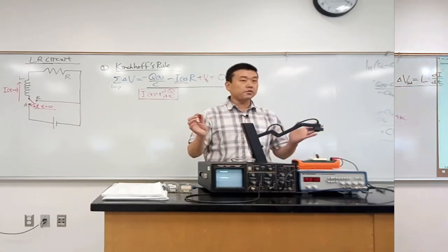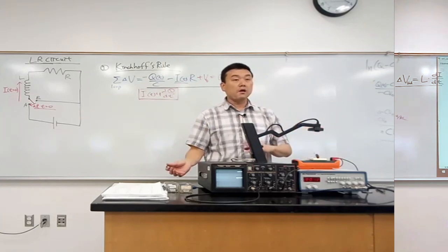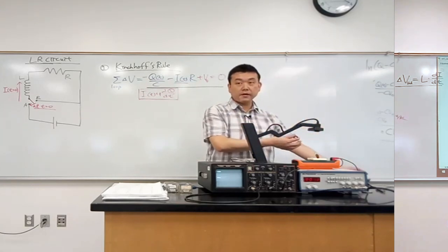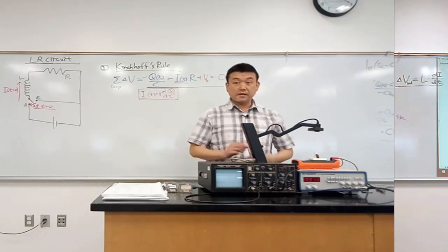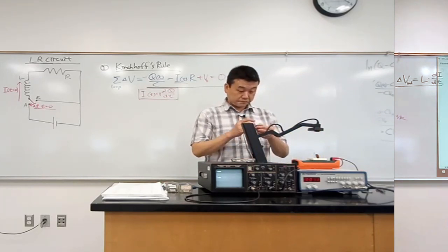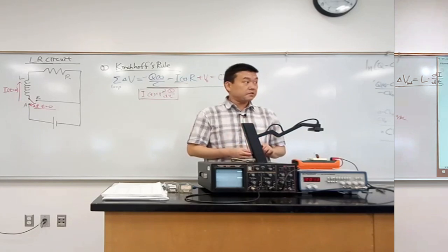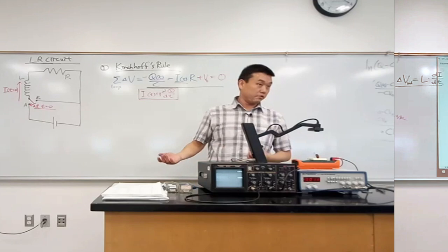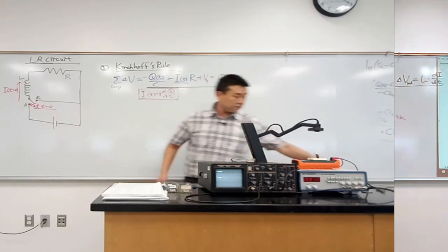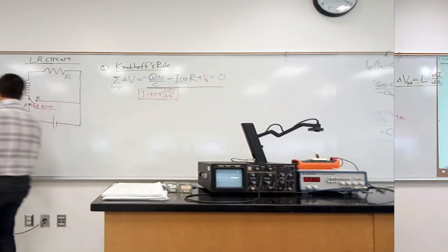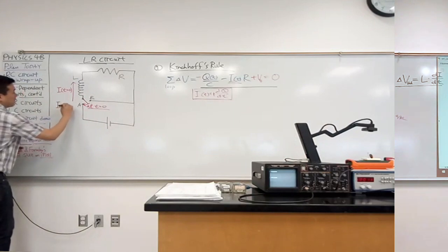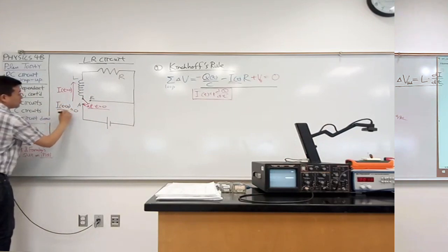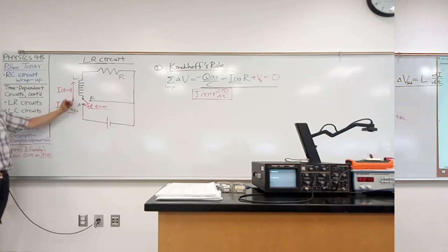Let's imagine all the different values that I could take, one particular value in one category and other values in a different category. Any value you think would be special? Yeah, 0 is a special value for many reasons. Here I can at least give you one other reason than the usual one. The reason 0 is special is the current at time less than 0 was actually 0, because that was before you connected it. The current through the inductor was 0 before anything was connected.